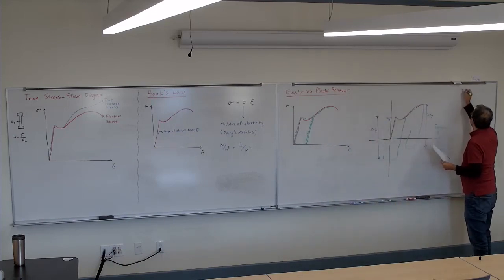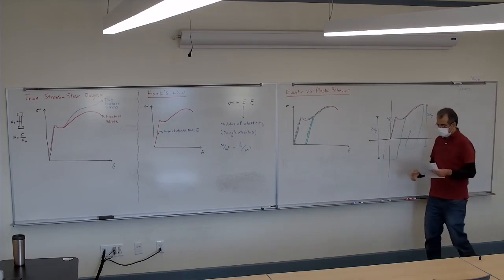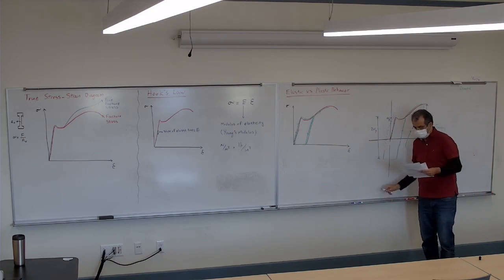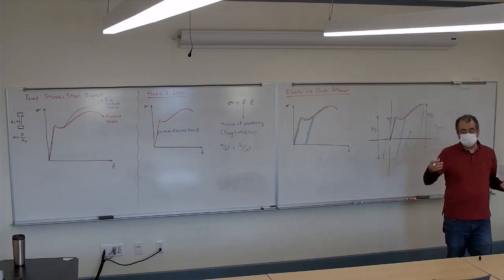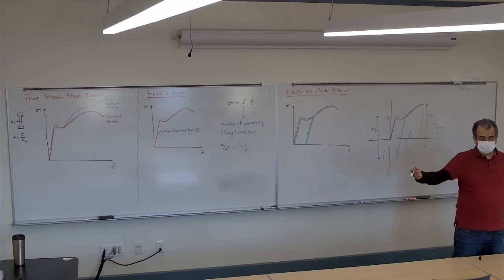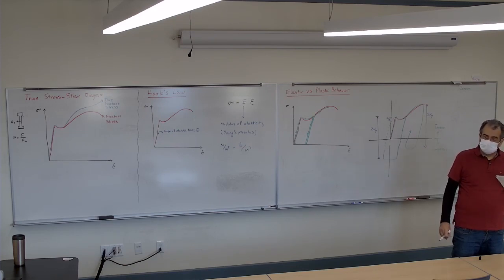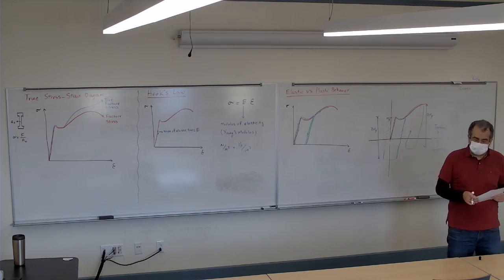There's a creep. You know what a creep is? If you put the load for a very long time on the member, even in the elastic section, the deformation will stay there. So even if we are in the elastic section, if we keep the load for a very, very long time, it never goes back to its original shape. So that deformation will stay there.